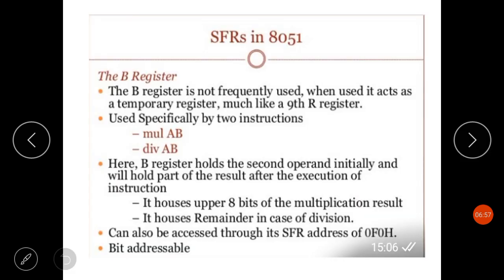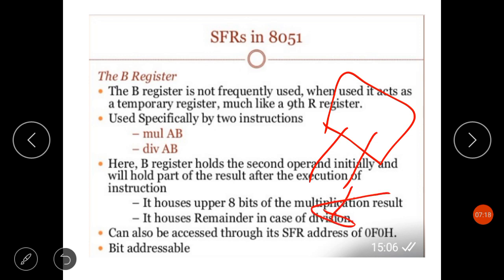The next register I am going to discuss is register B. It is a special 8-bit math register. It is used in conjunction with register A as an input operand for the ALU. As I've told you, the ALU needs two operands. The accumulator is used for storing one of the operands, and register B can also be used for storing the operands of the arithmetic and logic unit.